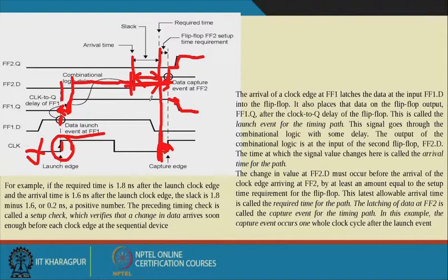which is not at all tolerable in chip design. So at that time you have to increase the clock period, or optimize the combinational circuit so that the data is stable before its required time. Okay. So here this is one example that has been taken to show you how we calculate the delay, how we set the corresponding clock period, and what the values of setup time, rise time and fall time are, and how they affect the timing information. Okay. So then again you see another example.